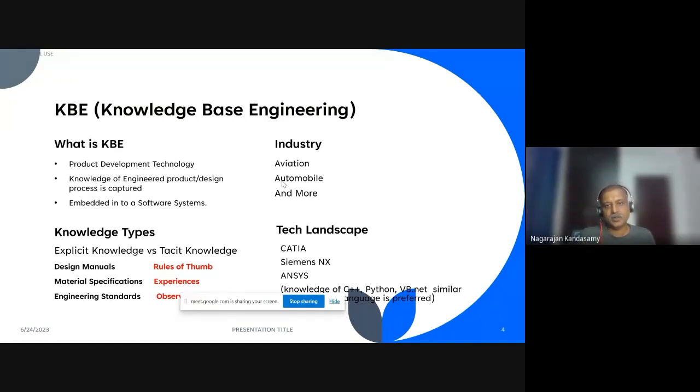So you have the design rule, you apply it, and you provide the input parameters like flow rate, what the temperature would be, and things like that. What is the fluid medium? Then the output would provide different types of shell and tube heat exchangers with different sizes and variations. So there are many variations, but they can be configured in a design rule. They are the ideal candidate for implementing KBE solutions.